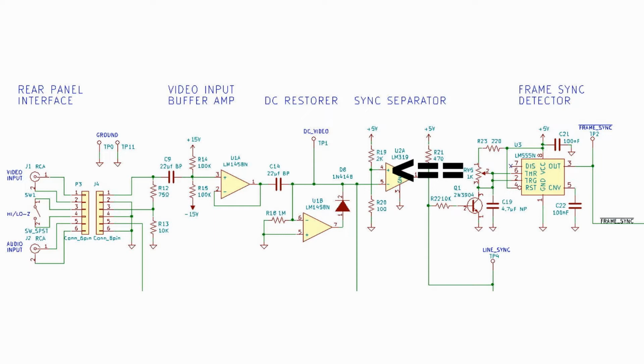The reference voltage here is just a fraction above 0 volts. You'll note that the divider consists of a 2K resistor in series with a 100 ohm resistor, so that the voltage on the 100 ohm resistor is only 100 or 200 millivolts above 0 volts, which puts it inside of the sync tips. So when the sync tip goes more negative than the voltage present on pin 4, the output of the comparator on pin 12 will be pulled high.